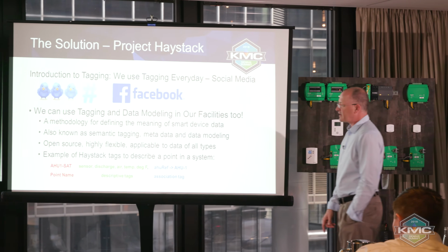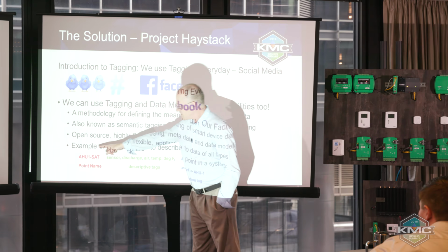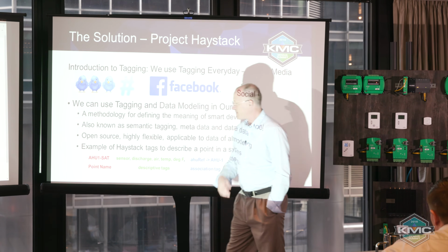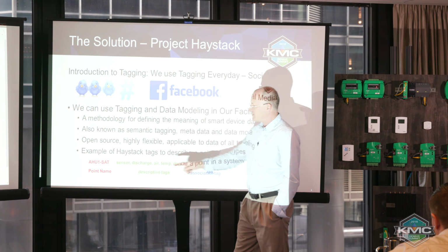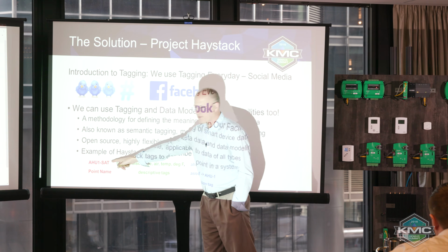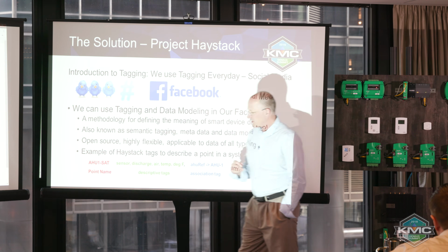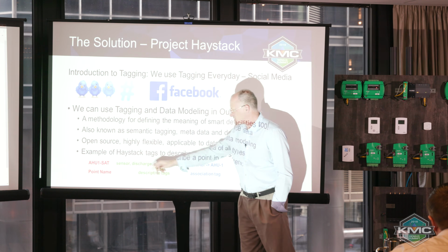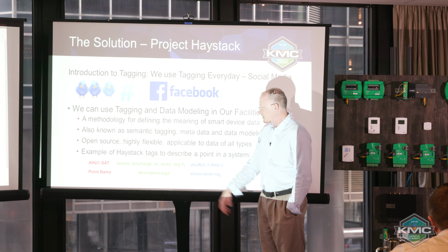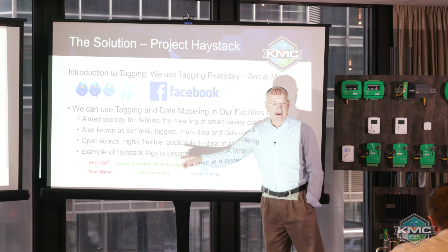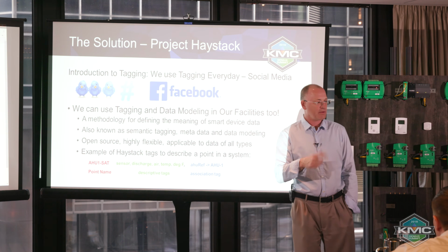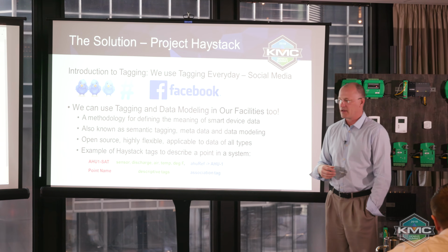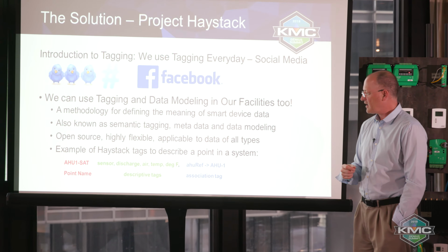So really all we're doing is taking, let's say, a point name, and in place of trying to decipher that as a human, we're going to add some metadata, which is, in this case, a tag called sensor, a tag called discharge, maybe air. Those descriptive tags will be in the database record while I'm creating it, and there's a lot of neat ways to do that very efficiently.